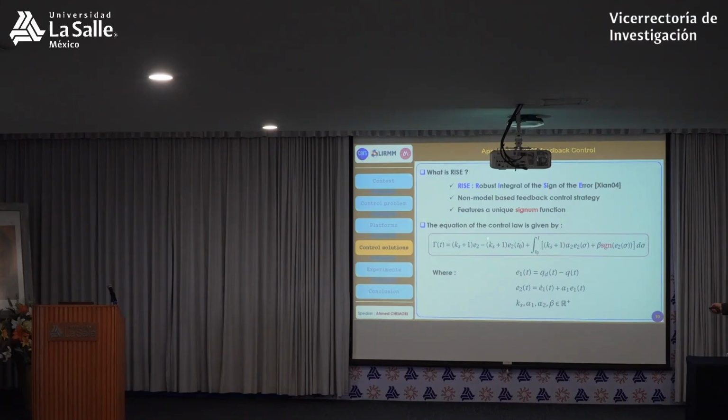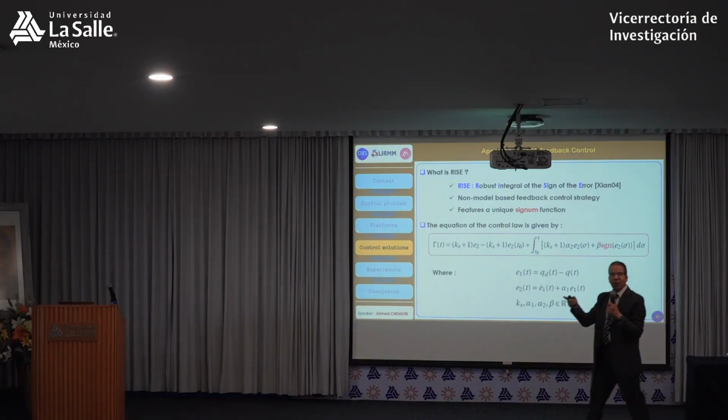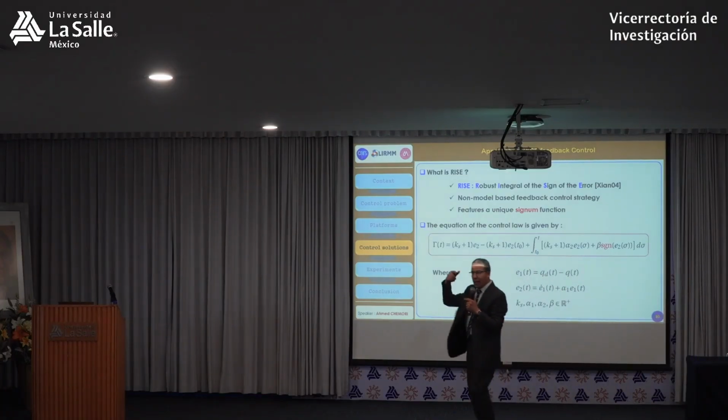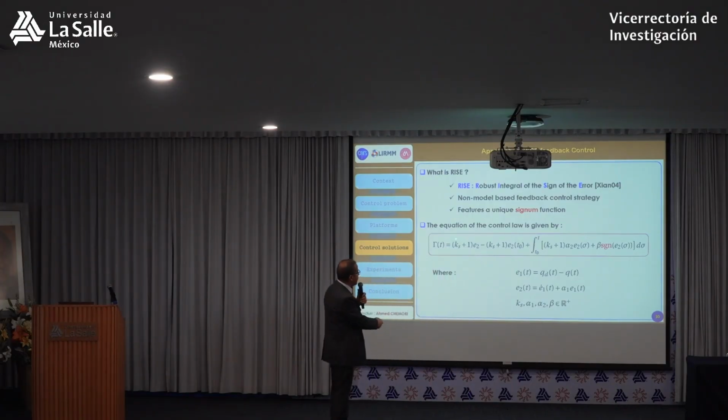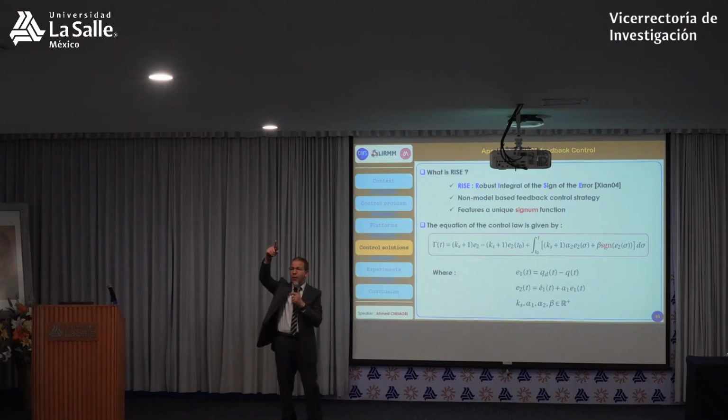Now, the last term that I didn't explain here: if you don't put this term and you design a controller and you have an initial tracking error, you can start with a very big control input. If the gains are big and at t equals 0 there is a tracking error multiplied by big gain Ks, you can have a very big control input. So you may start your robot with abrupt, big motion.